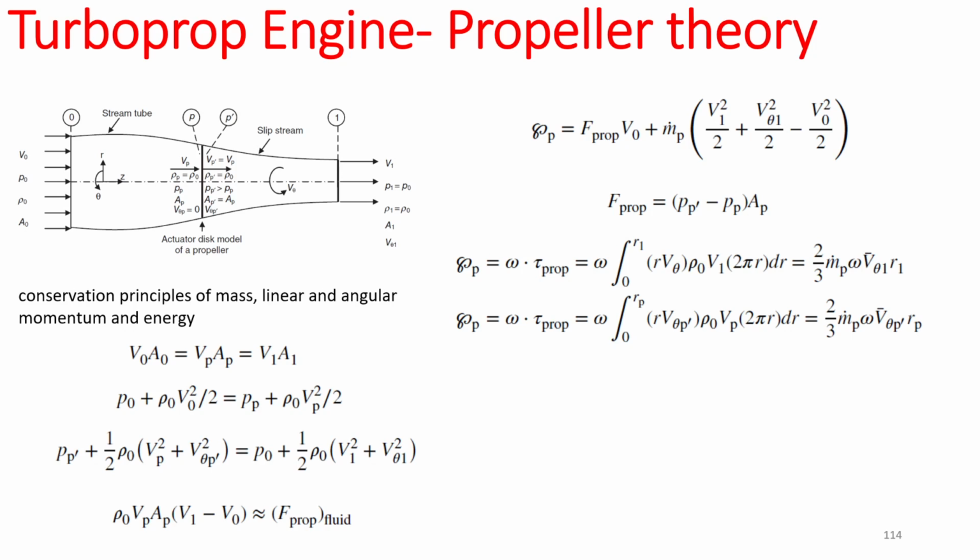So we are talking about these two equations, they talk about the conservation of angular momentum, right? What is the angular momentum before the disk? Forget about the equation, just answer my question. We have fluid swirling here, and we have fluid not swirling before the disk. What will be the angular momentum before the disk? So we write the conservation of angular momentum for the after-the-disk condition. We can actually write it for the whole thing, but then it defeats the purpose because we will have an unknown, the influence of the disk, right?